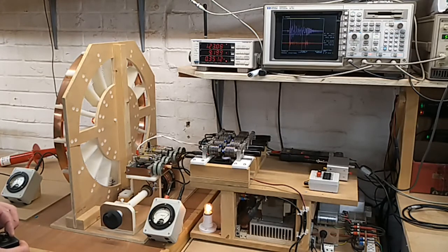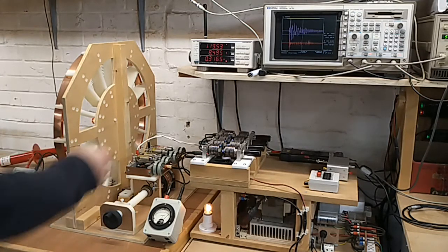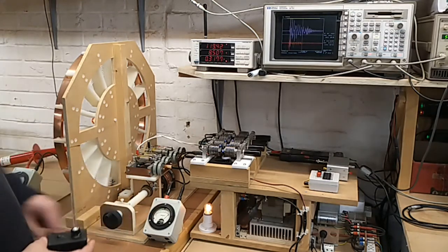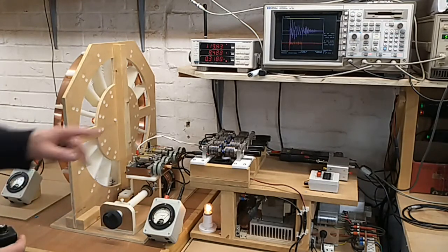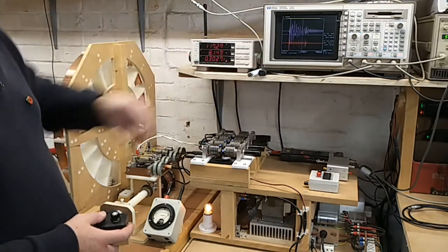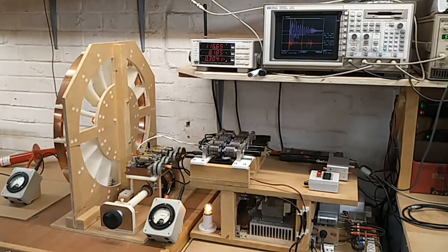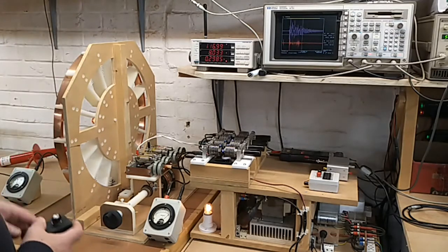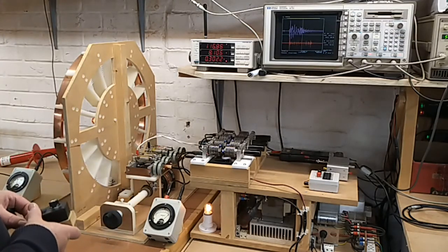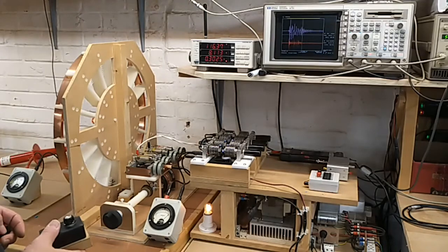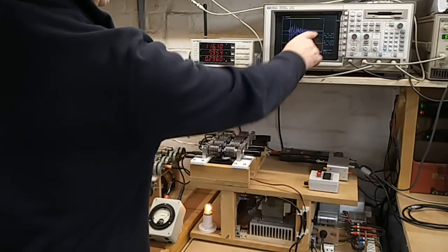Here we are, running about 300 watts in as before. Spark gaps are nice and steady and stable. We're reading about 4 amps RF current in the primary circuit, and we can see obviously this is showing the burst waveform that we get. So the spark will be operating at 100 Hertz. That's the positive and negative cycle of the line frequency, which is 50 Hertz. And then we're triggering at the beginning of the start of the discharge. So this represents a discharge burst